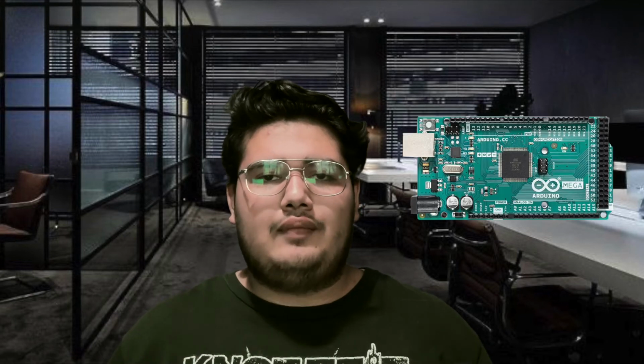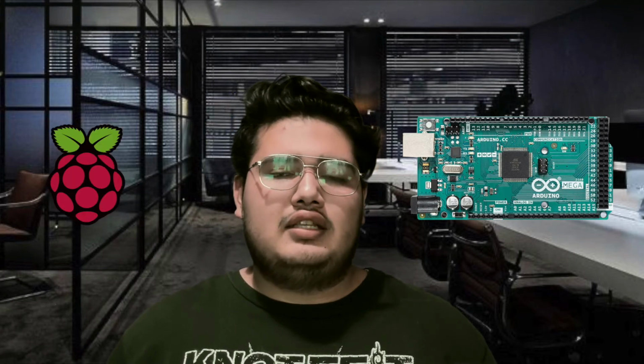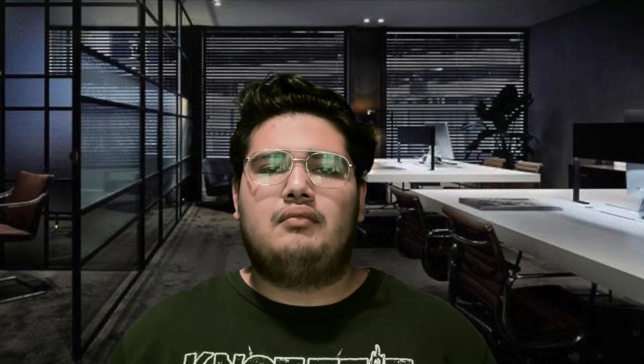Last but not least, and in order to make a fine prototype, we developed a complete car luxury design using the microcontroller Arduino Mega. We control the Arduino with the Raspberry Pi by sending bits to the Arduino ports, using pull-down resistors, avoiding high impedance.